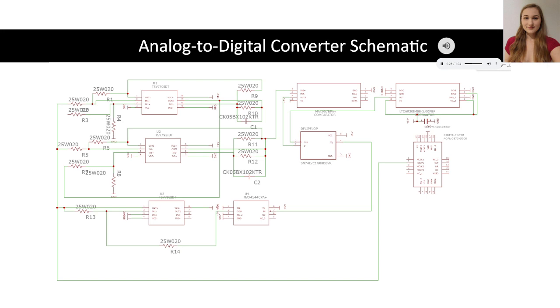That goes into a D flip-flop. The D flip-flop compares the signal in with a clock signal in the megahertz. This oversamples the signal. It then goes into a switch, which checks if it is greater than 0 or not. If it is greater than 0, it gives 5 volts. If it's less than 0, it gives negative 5 volts. That then goes to an inverting op amp and back into each of the original op amps at the beginning